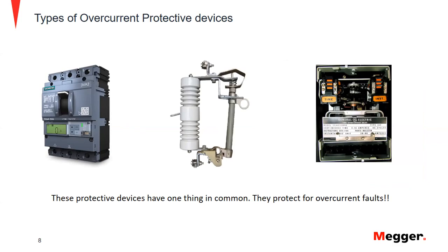The first one that you have is a molded case breaker, and it uses a bimetal element that is heated by the load current. So when an overload or a short circuit occurs, the bimetal inside the molded case breaker flexes and kicks the breaker off a latch. And so it breaks the circuit inside the molded case breaker device and the housing.